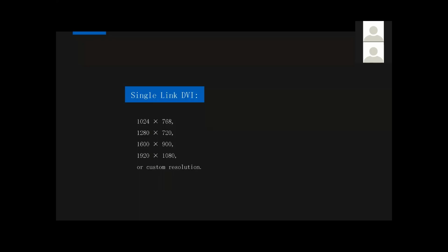So we know we use HDMI 1.3 or single link DVI connectors. By checking all supported input resolutions with single link DVI, the maximum input resolution is 1920 by 1200. So the total pixels will be about 2.3 million pixels. Which means 2.3 million pixels is the maximum we can get from the source. That's why 2.3 million pixels is how much we can output with all 4 ports.